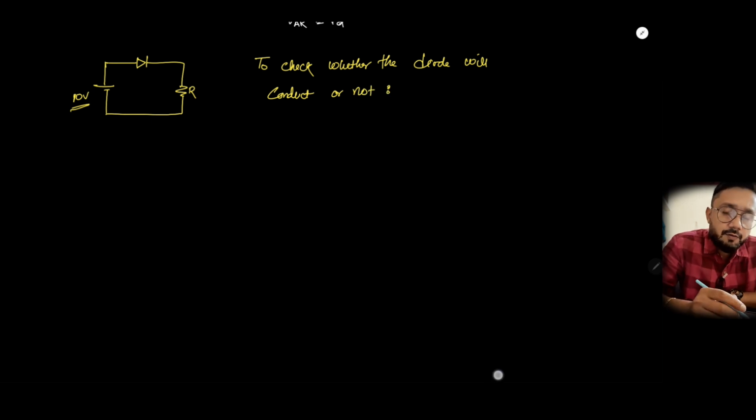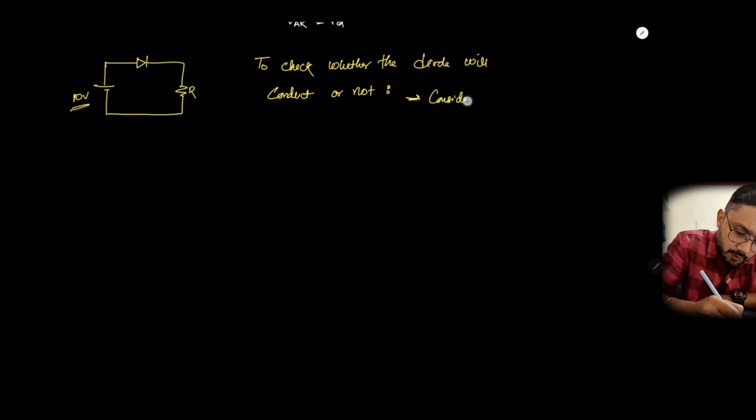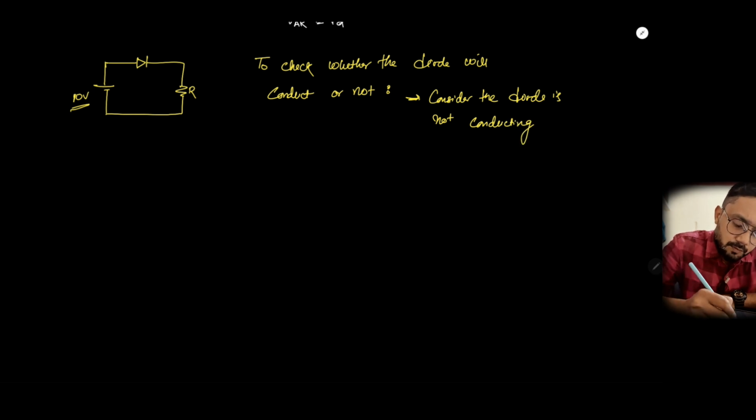To check whether the diode will conduct or not, you consider that the diode is not working, that is, it is in an open circuit condition.